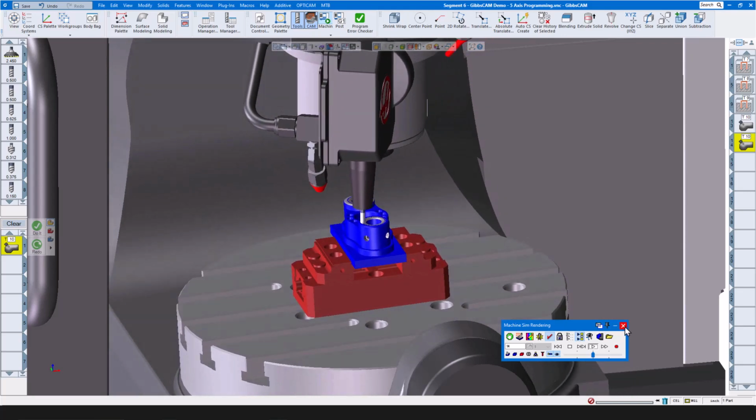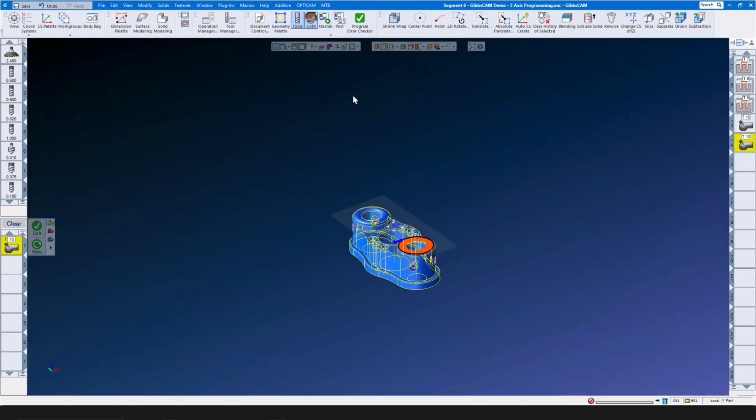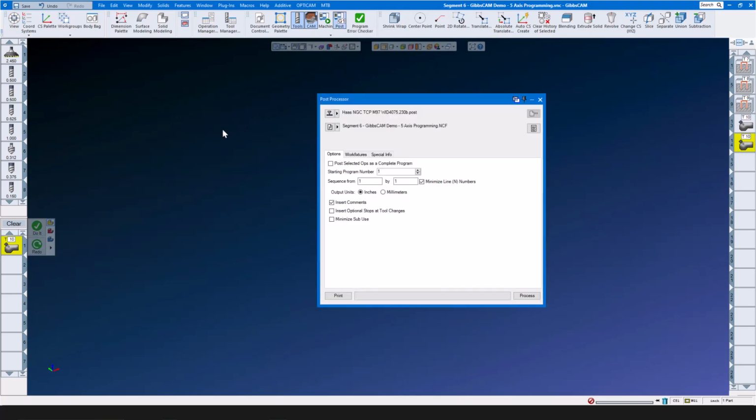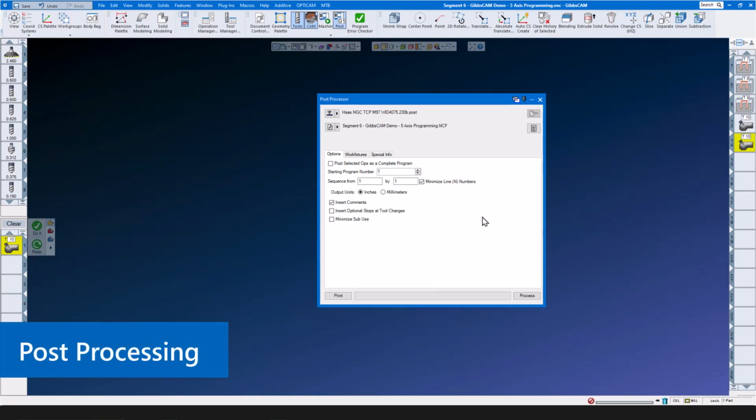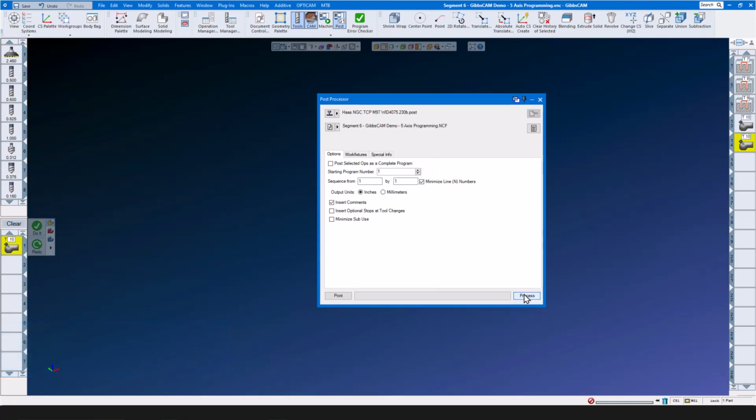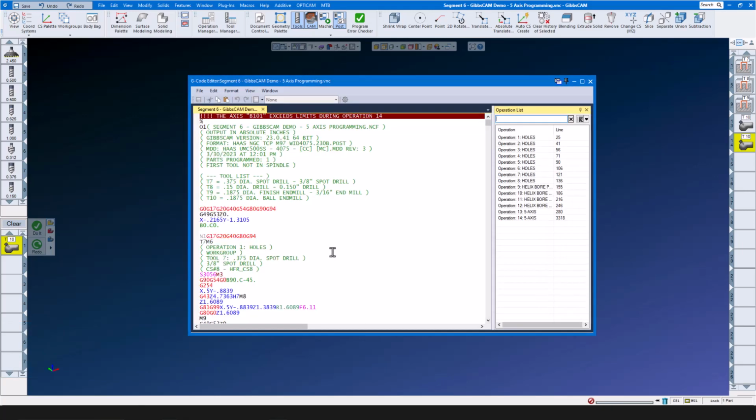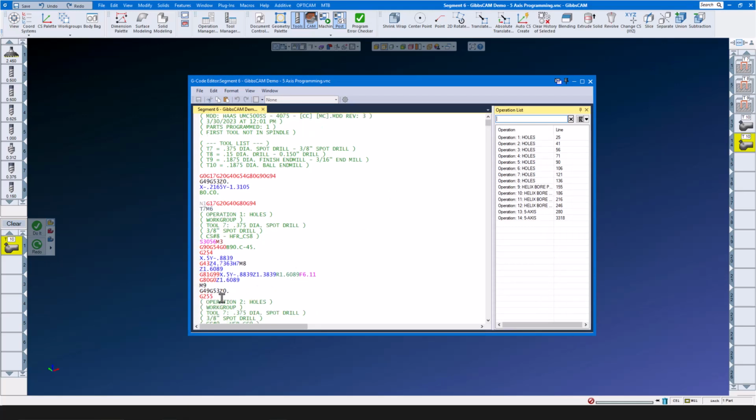In 5-axis and 4-axis CNC machining, there are new items that are inside of your controls, such as tool center point control programming, dynamic work offsets, and other unique features for your 4 and 5-axis machines. Here in the code, you'll see right at the top of the program G254 and G255, which is dynamic work offsets.